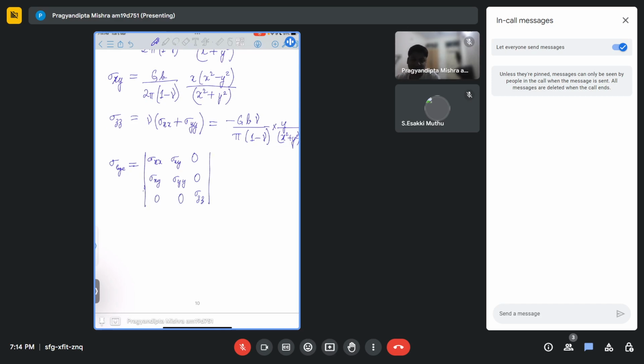Similarly, the strain tensor will also have the same components. One important thing you can note here is that this is exactly the inverse of the screw dislocation tensor, because this has exactly the quantities present in the stress or strain tensor which are not present in the screw dislocation, and vice versa. So this is the importance of classifying edge and screw dislocations.